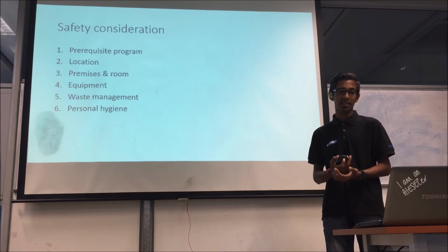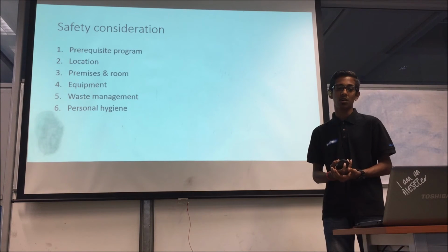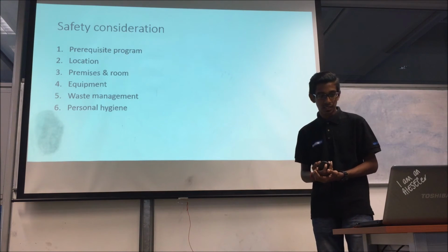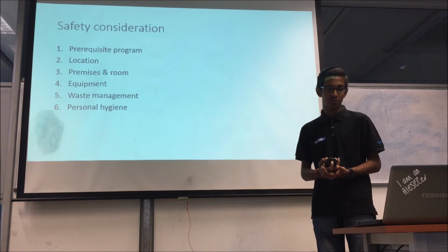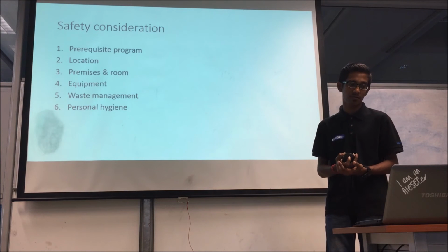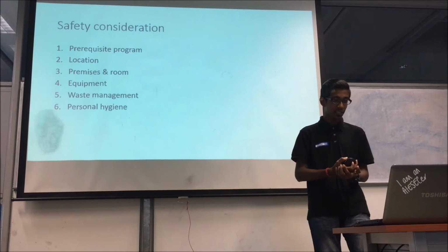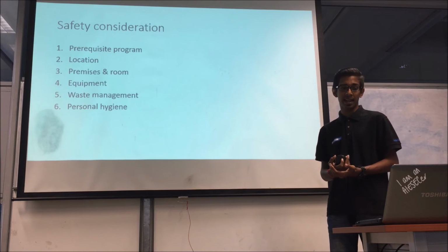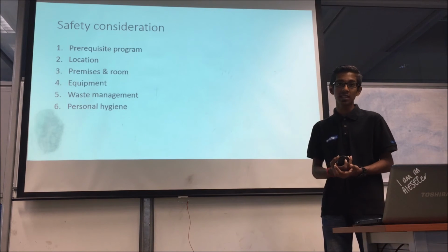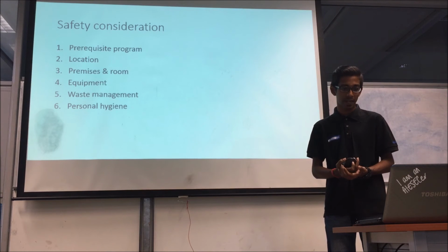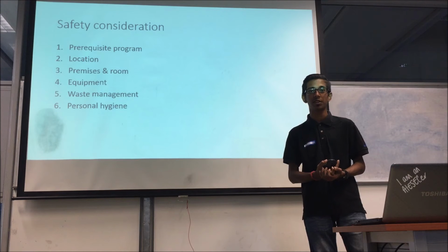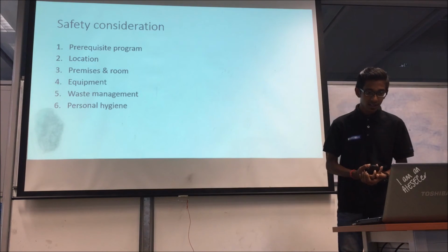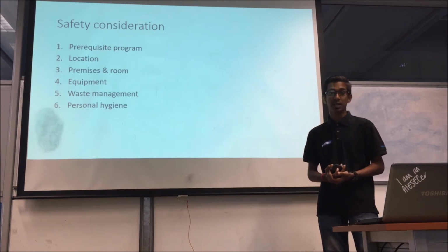The floor is epoxy and at a certain height the wall is covered with epoxy for easy cleaning. The doors and windows are made of glass covered with finished aluminum structure and 6 exhaust fans maintain fresh airflow which reduce heat vapor and thus maintain relative humidity and temperature. Next is the equipment. The equipment is stainless steel and other materials that are suitable for food industry and design construction is easily maintainable. All equipments are checked routinely to ensure a smooth running system and free of crack, rust and dents.